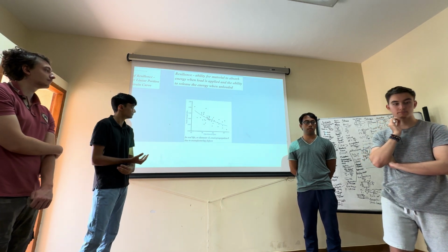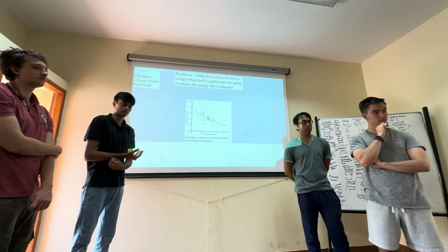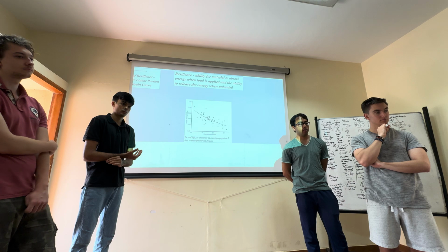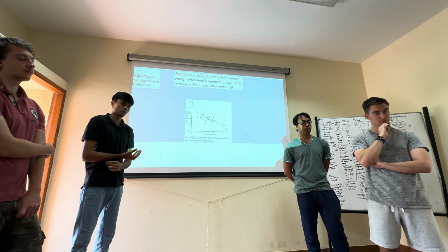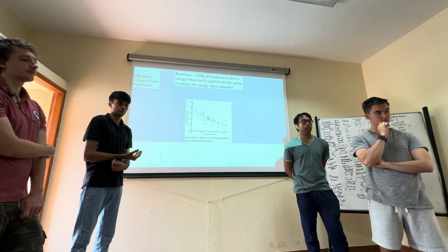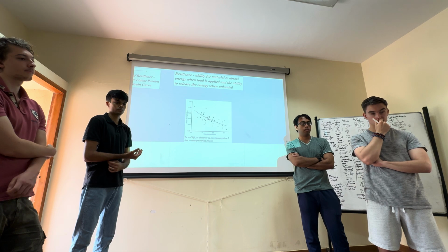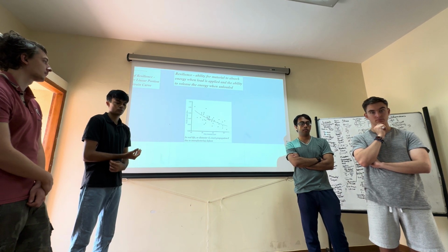While manufacturing is the main reason you would have defects, even if you manufacture with a very low defect density, the handling process can always induce them, because these are very flimsy. How you protect and transport them will matter in terms of the defect density when you actually utilize it in a composite, and then in a structure.